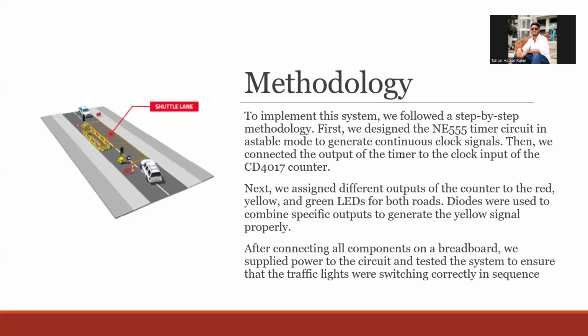Assalamu alaikum. I am Tahsin Ibrahim. My ID is 242-15537. Now I will explain the methodology of this project. First, we designed the NE555 timer in astable mode to generate continuous clock pulses. Then we connected it to the CD4017 counter to control the sequence.